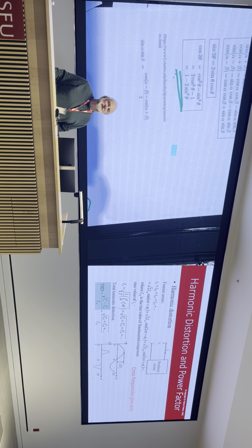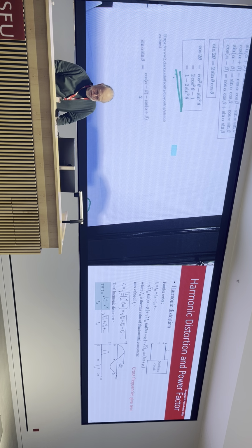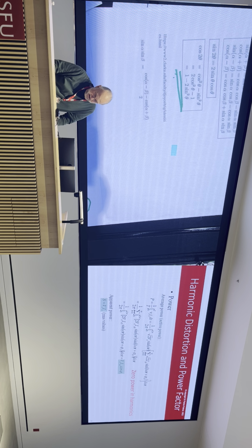What I'll do is I'll do it in LT Spice, because that's easy, right? LT Spice will sketch it for me another time. Average power, 0 power in the harmonics. So what we really want then is, to get the actual power out, we need the fundamental value of the S1, the current in the source, and we need the cos phi angle, the power factor angle, but with displacement as well.